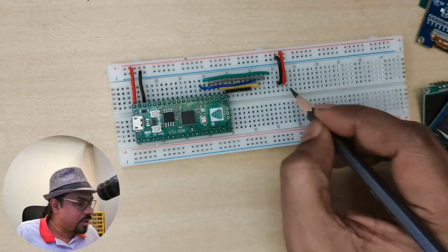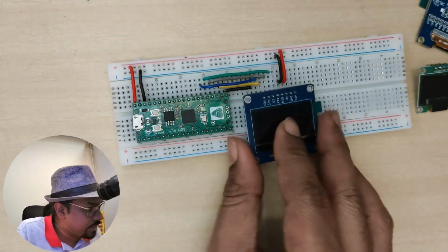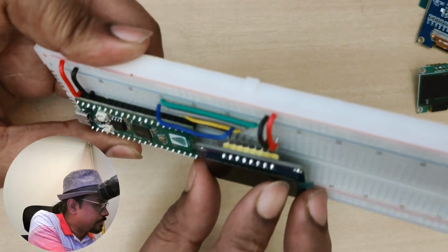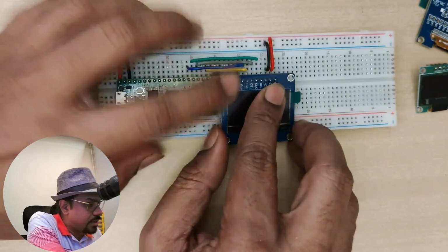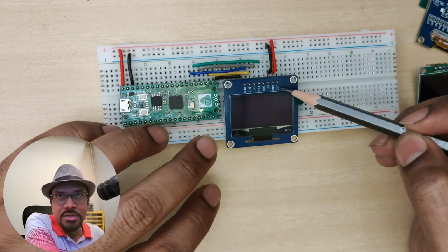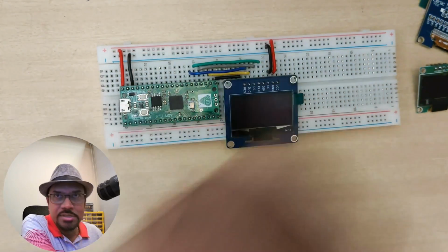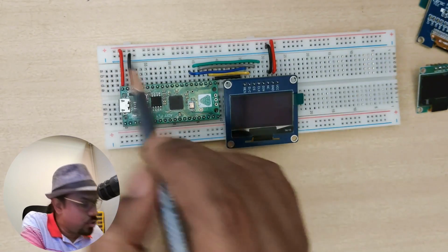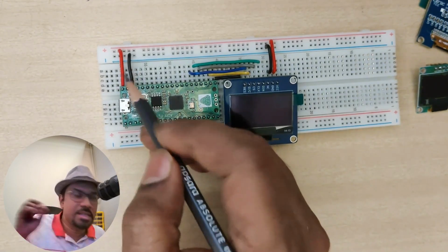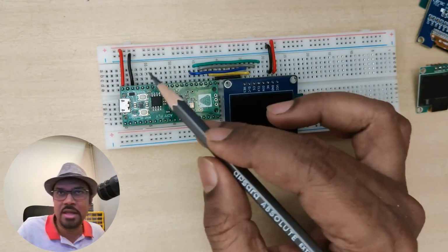So if you connect the display in this place, it's meant for this display. If I put this display in place here, like so. Yeah, just trying to show you. You can see that this is a VCC pin on the display, which connects to the positive of the power supply coming from the micro USB through this Raspberry Pi Pico. You can either connect to VBus or you can also connect to the next pin, which is the VSys pin. The next immediate pin is VSys, which is nothing but a regulated supply coming from the Raspberry Pi Pico. But if you're using a breadboard power supply, that's where it will be connected to.